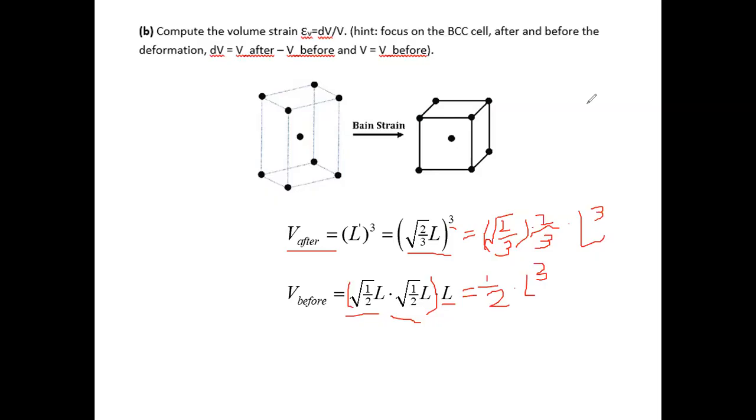And as we can see, if we have a change of the volume, this means that if some region of the system undergoes a Martensite transformation by switching from the FCC to the BCC, well, this means that you're accumulating a possible strain energy, right? Because you have a volume change, which is not small. This is a fairly large volume change, like 10% at least on that level, right?